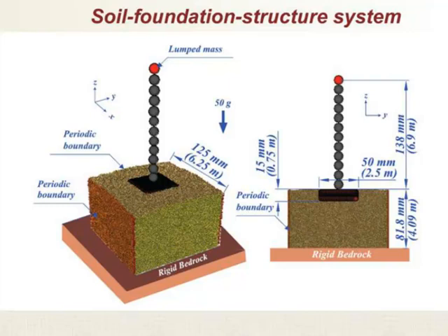One of them is using the high gravitational field that is used in centrifuge testing. We heard a little bit about centrifuge testing earlier today, and the idea is that by subjecting the system to a high gravitational field, you preserve the stress level in the soil deposit at values that are similar to a prototype, meaning an actual field condition.